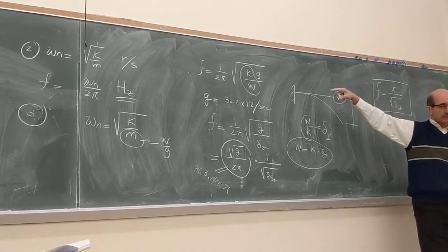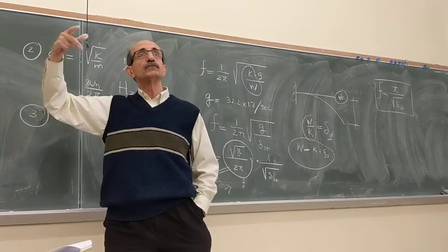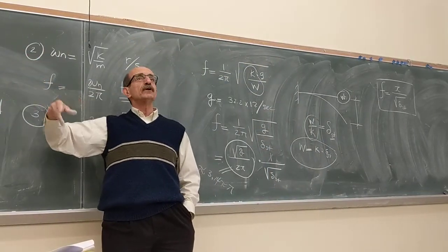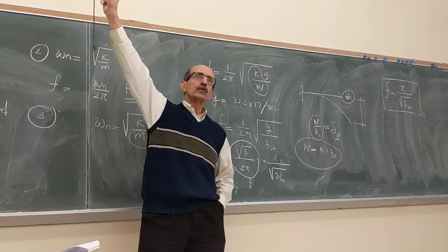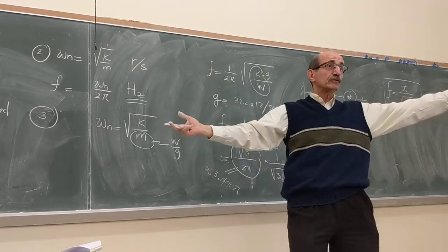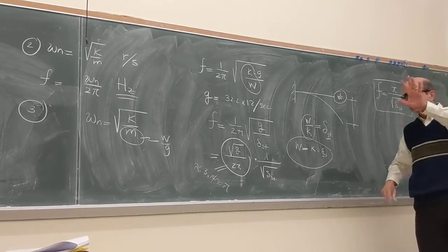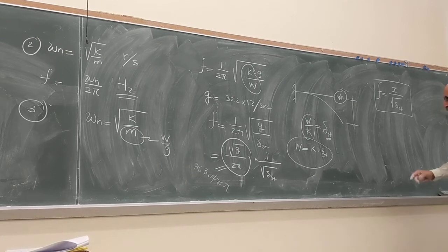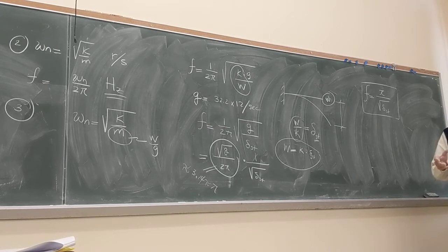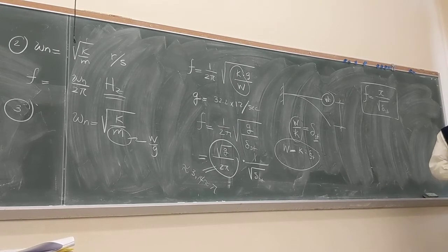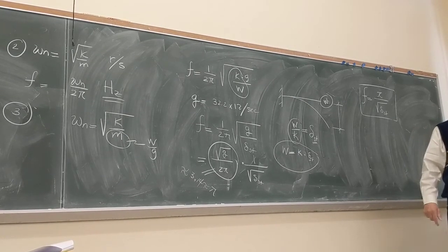One of the important things about natural frequency is that if you have a forced vibration and the frequency of the forcing function becomes very close or equal to the natural frequency of the system, the response of the system goes to infinity, or the system would collapse, because the amplitude increases and increases. We'll talk about that, which is called the resonance phenomenon. So these guys wanted to find out if it is adequate to assume that the natural frequency of this offshore platform is way away from the forcing function frequency.